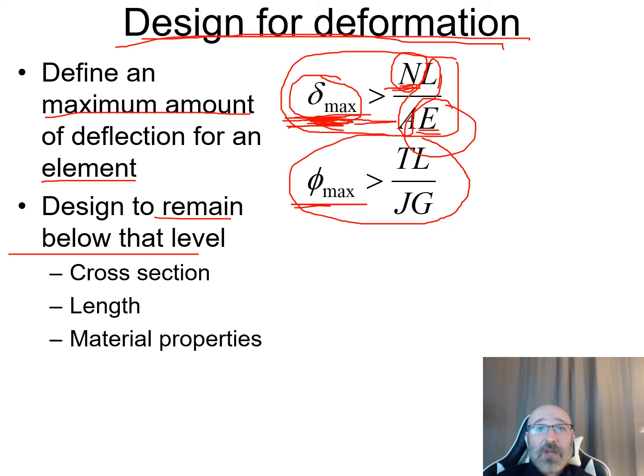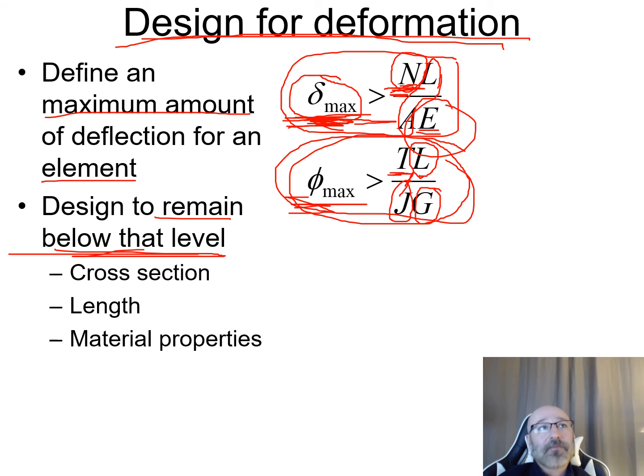In this case, maybe we know our torsion and our modulus of rigidity. Then we need to calculate our L, and we can look up our relationship for J, and we do the same thing we did up here, but now we're dealing with torsion rather than just an axial load. Or maybe we know the torque applied from the motor and the generator, and we want to figure out the dimensions the shaft needs to be in order to stay below this max level. So that's another example if we're dealing with torsion rather than an axial load.